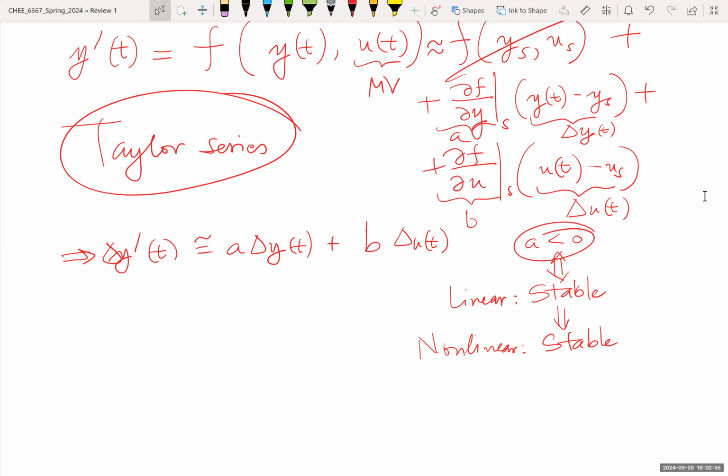Theory guarantees that. It just doesn't tell you how much that is. But you can find that with simulation, like I said, fairly well. So it's practical. This approach is very practical, which is why people use it all the time. Most, if not all, controller design for chemical plants at that level is done with linear systems. The only thing that people may linearize, but that's an easy one, is this delta U.